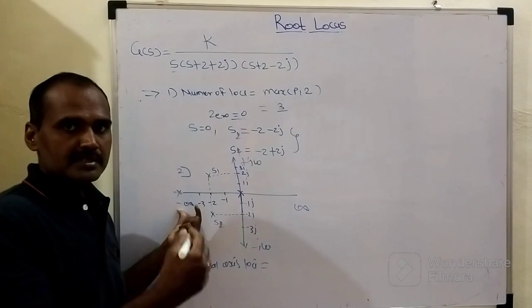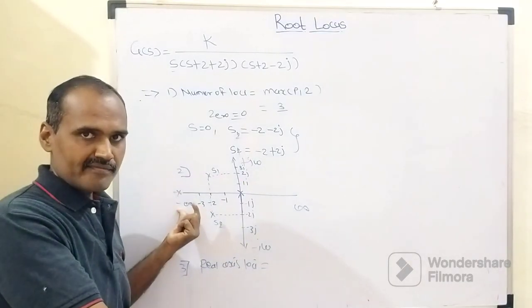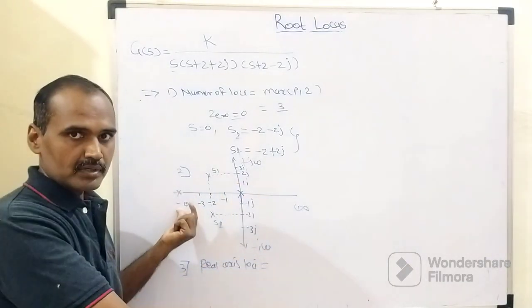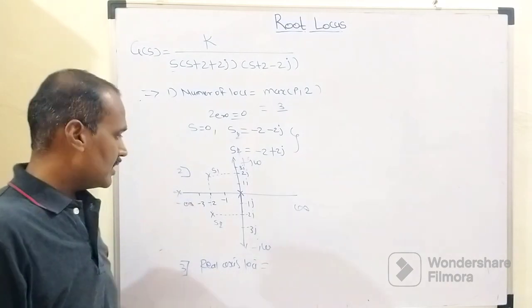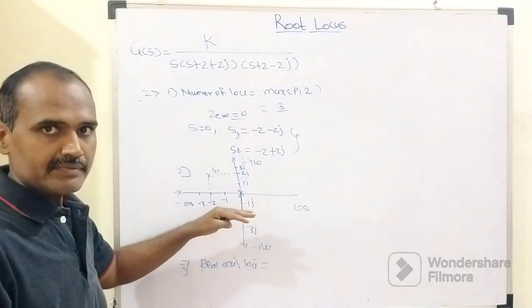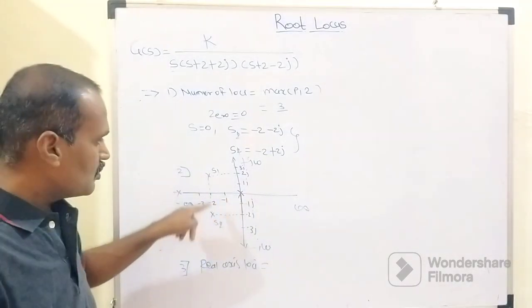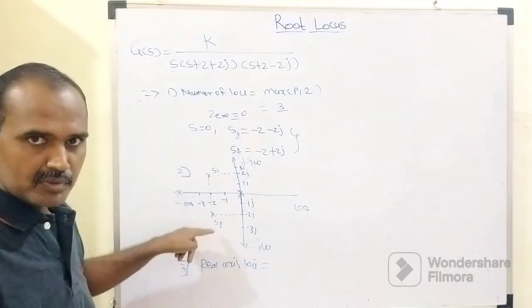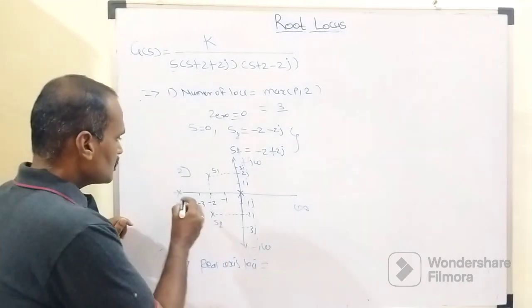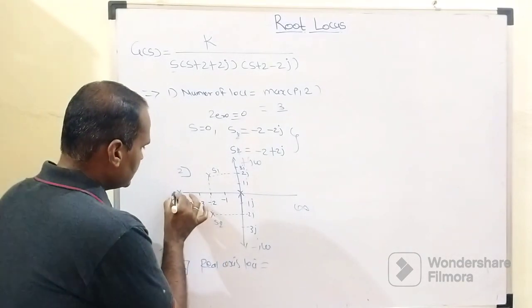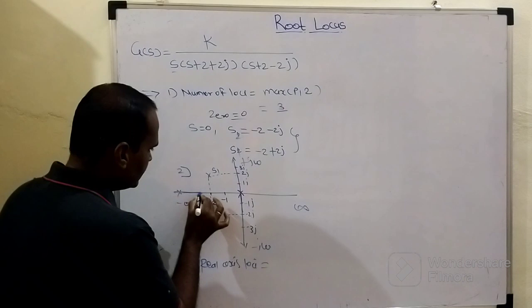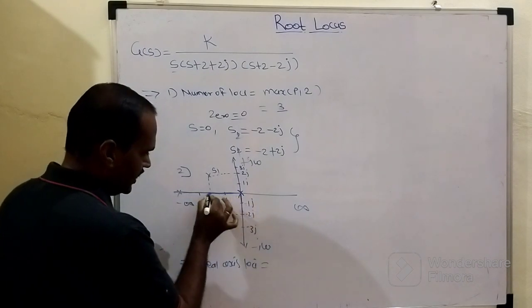When we count, this pole is considered as a reference pole. So ultimately, towards its right-hand side, how many poles do we have? Always three different poles. One is located at origin, and another two poles are located at quadrant number 2 and quadrant number 3. So this root locus is present in between minus infinity and 0.